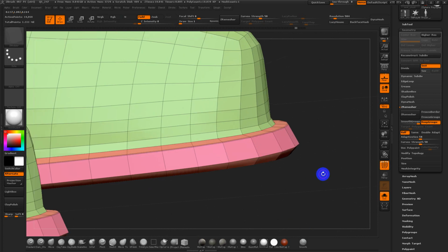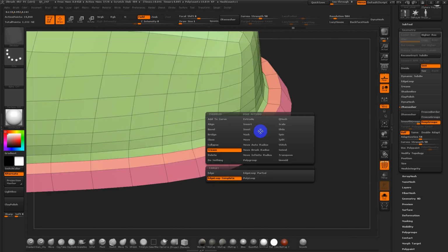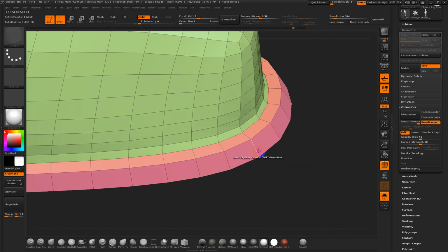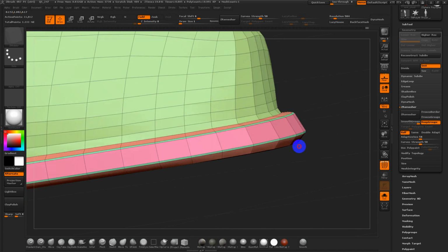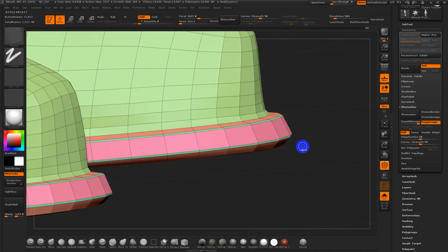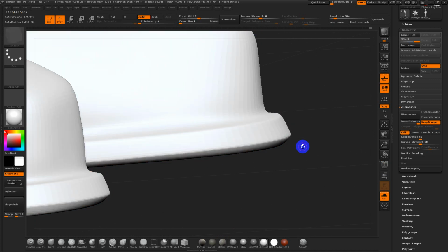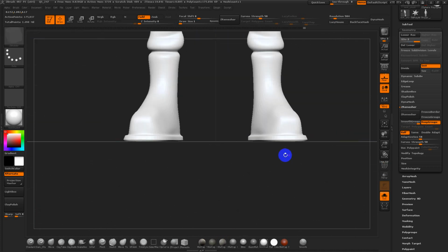Now, I wouldn't usually crease. I would actually prefer to bevel instead. So what's the tool? Yeah, bevel, edge loop complete. So that way there's actually 2 real loops. So doubling the loops there, doubling the loops there, because that will actually translate properly to Maya. So now when you hit, again, test it here, Control D, you're seeing that kind of sharp.